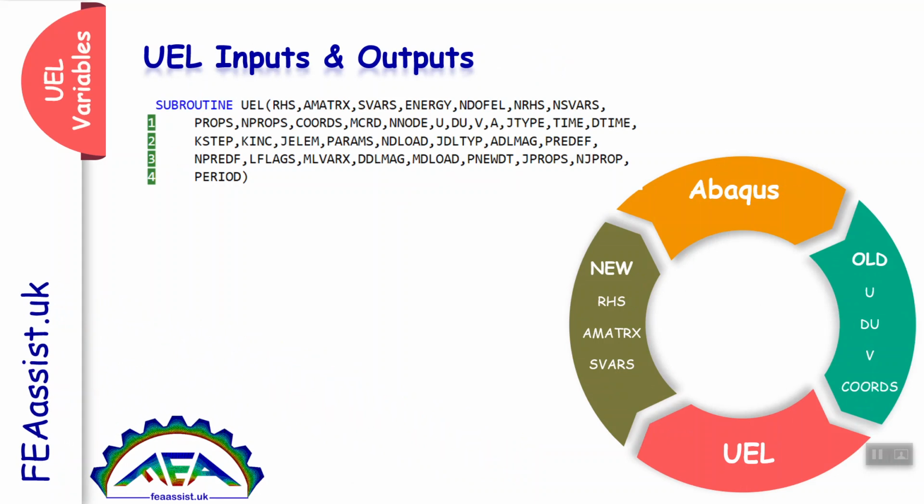Again, Abaqus gets these variables and computes the U, dU, V curves. This is how Abaqus and UEL interact with each other, which is necessary to well understand to write well-working UEL subroutines.